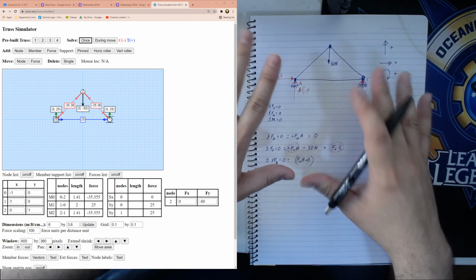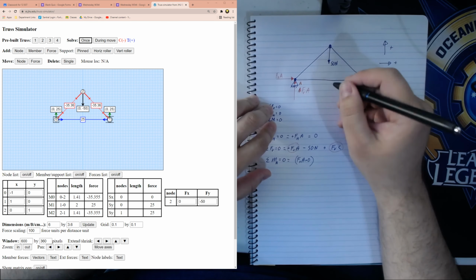Oh, I need to show you some distances. This over here is 2 meters, and this over here is 1 meter high. So this 50 newtons is minus 50 because its force is 50, and its distance is 1 meter because it's in the middle of this 2. We have that, and then our last force is this one over here, where we're going to have force VC. We don't know what force VC is, but we know its distance is 2. And this over here, if we have the bridge over here and this is going up, it's going to be